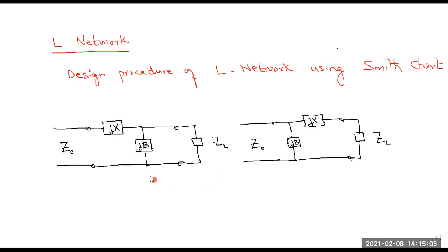During our last lecture, we outlined that whenever you design an L network, you have to take two steps. The first step is to select the proper L network for the given load. Only one of these circuits will be useful for us.